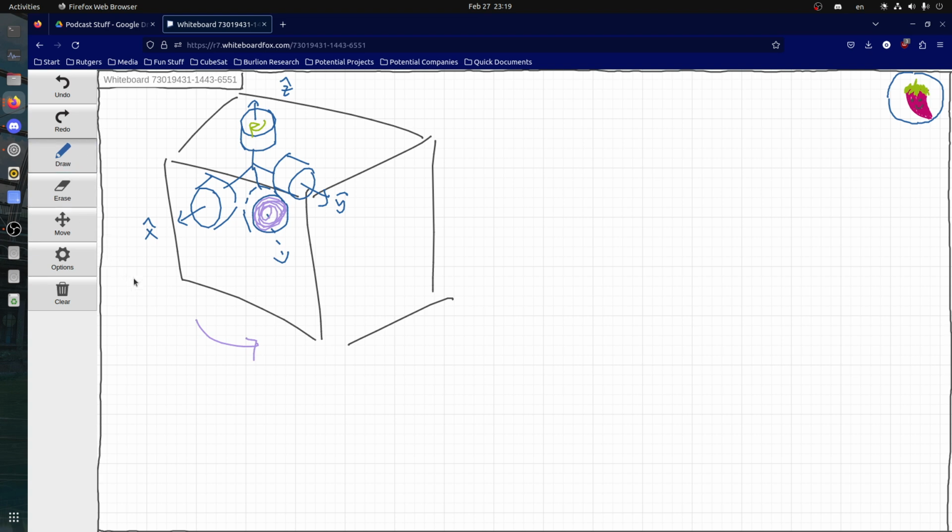So for the reaction wheels, usually it's good for three-axis control. If you have three wheels, you can rotate all three at different speeds and get them to any attitude that's possible. And their accuracy can be pretty good. Usually, less than 1 degree is normal. However, this does require electricity and a controller, and because it's a mechanical system, there is a spinning wheel.